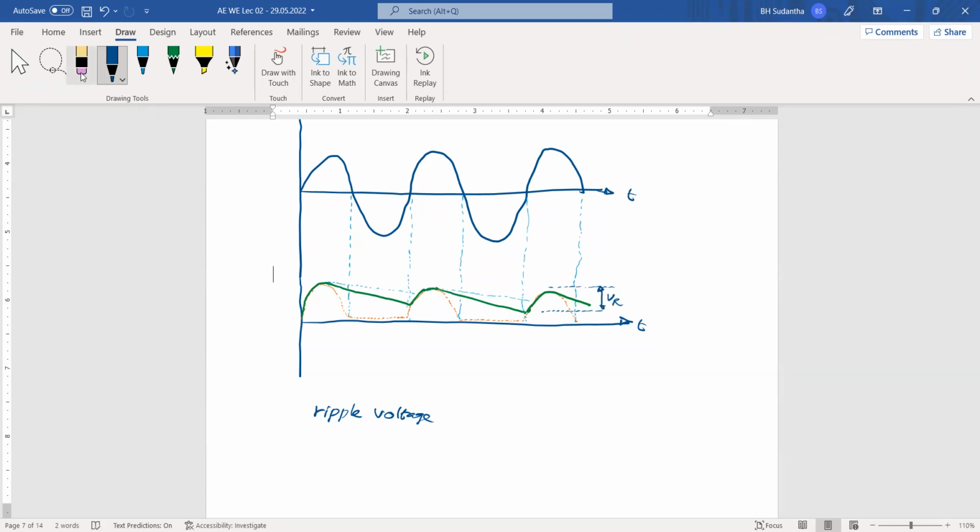Sorry, if you put capital R, it may be another confusion, so we can put simple r. Ripple voltage Vr can be reduced if we increase capacitance. But we have to remember that we cannot include much larger capacitors without considering the capability of the input side.